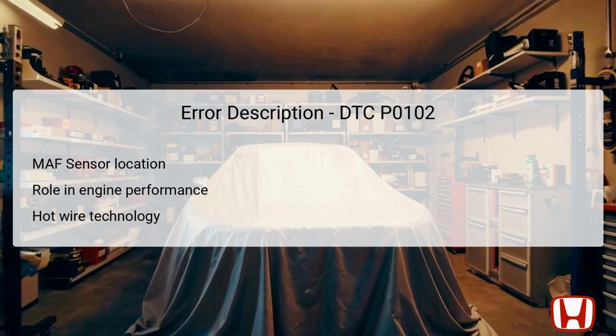The mass airflow sensor is located on the intake air passage of the vehicle, directly interfacing with the air entering the engine. This sensor plays a pivotal role in measuring the volume of incoming air to inform the engine control module precisely how much fuel to inject for combustion.